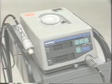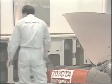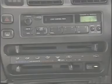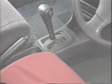Now, let's see how to adjust the idle speed and mixture. You should use a CO meter to do this if possible. First, in order to adjust the speed and mixture properly, we must make sure that the following conditions are met. Make sure that all the electrical accessories are turned off. Check to see that the transmission is in neutral.